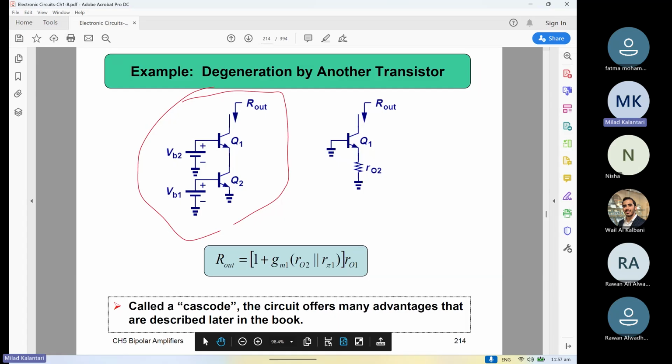Basically, it is trying to say that the first section is just nothing more than one R out, right? It is just simplifying. Let's say the AC small signal model for Q2. Here you just put a short circuit at the base, and then from the collector perspective it is only RO2, right? It just remains one RO2 at the emitter of the top one.